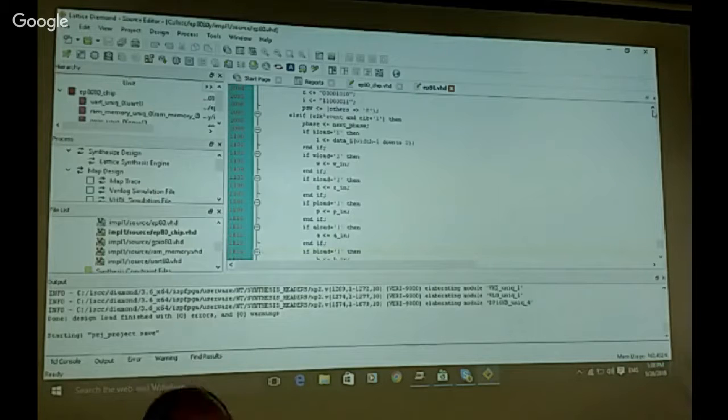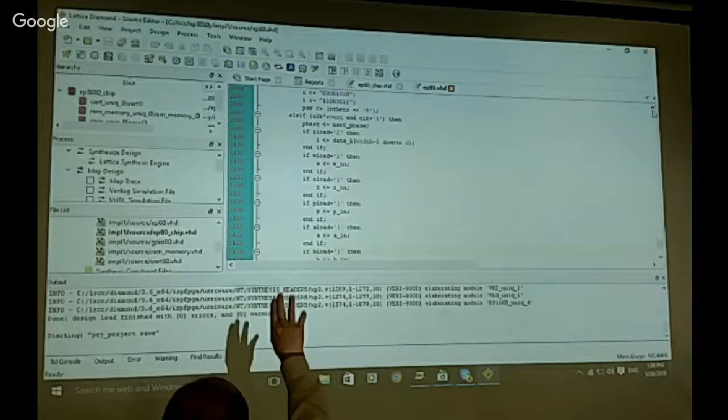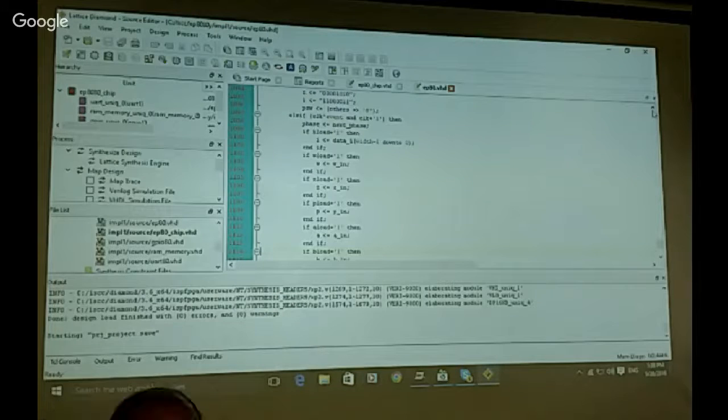But for each instruction, if you don't mention next phase, it will be 0. It automatically is set to 0. So these automatically execute as one cycle instructions, unless the instruction changes the variable next phase. Okay, when that's taken care of, then it's just looking at the load signals. If any of the signals is a 1, then we write the input to the register.